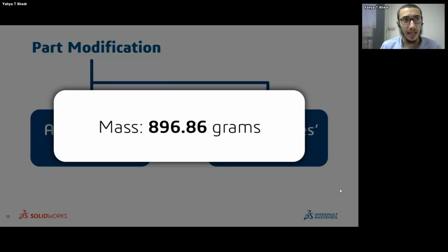So if I had taken some time to make sure that everything is set up correctly in its own feature, maybe in the first stage, that would have made it, using Instant 3D, very easy to just highlight, change the value, highlight, change the value, without modifying any sketches, without modifying any features, everything just from the outside, you know? So that would be a much bigger time saver in terms of the design. But at the end of the day, we still ended up with the same 3D geometry. It's all about how we reached there, how we approached there, okay?